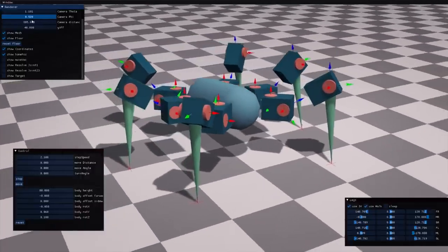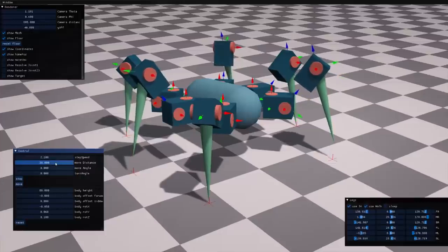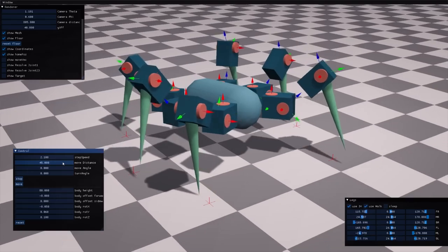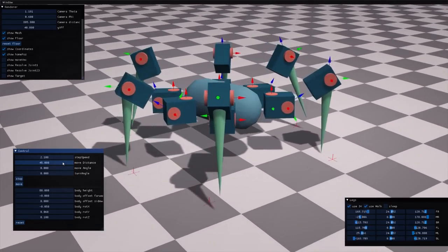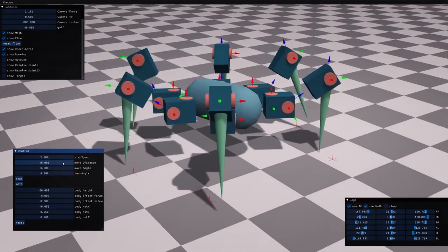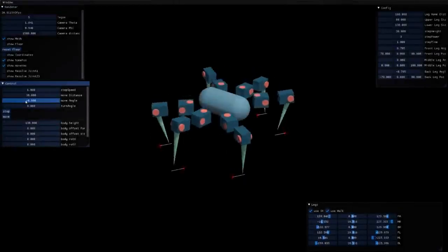Anyway, with this ready, I could try to solve the walking cycle problem. The hexapod always has 3 legs on the ground, and when it moves, you want to keep the distance between those 3 legs the same. Otherwise, it starts dragging its feet, and that's something we want to avoid. So you want to move those legs in the same direction and the same speed at any time.